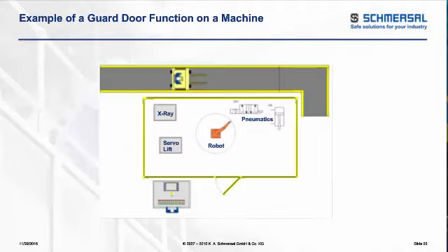So as we look back at our pictogram again, we see that guard door with those 4 different hazards. As we go through each one of those, we can now see, okay, we looked at the robot controller. We used a robot that has a controller that has proper safety input circuits for a guard door interlock to lock that robot into position when a guard door is actuated. And we check that off of our list because we've checked the schematics.